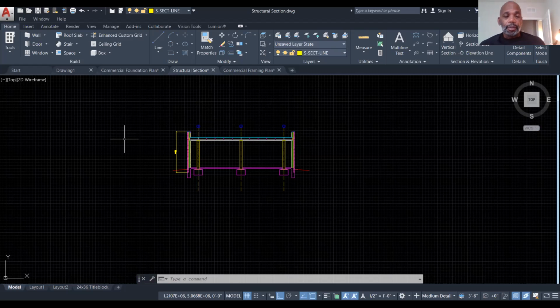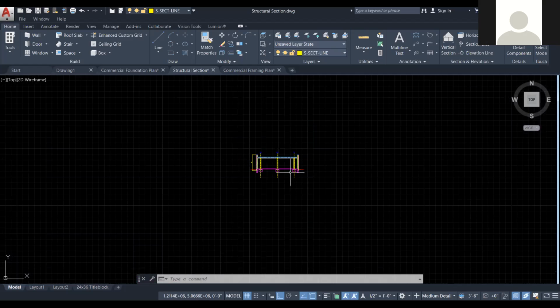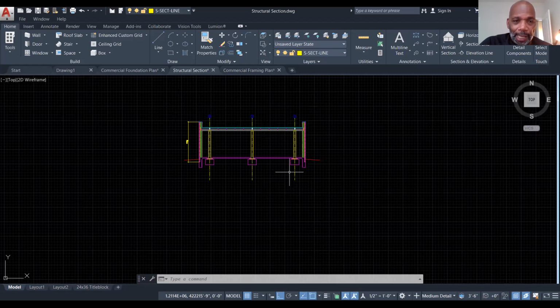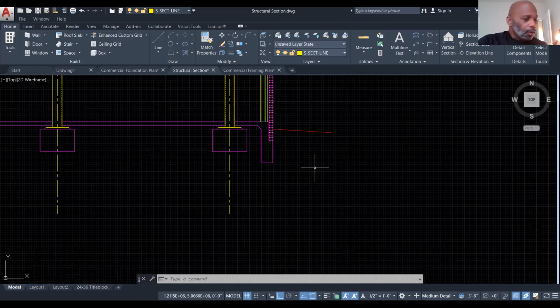Okay. After we do this, if you want to open it up in regular AutoCAD, you'll be able to access the standard hatch patterns. It's worth a shot, I guess. Yeah, it is. I've been trying to load the ACAD pat file, but haven't been successful. But I do know that's one alternative. If you just, again, open up in regular AutoCAD, the hatch patterns are going to be there and you can do your hatching. Okay.